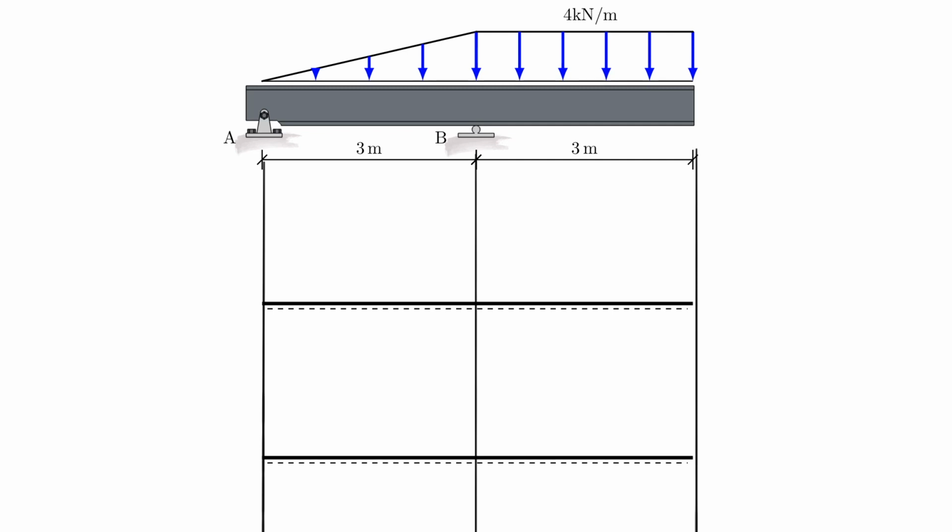All right, let's go ahead and start with the shear force diagram here on the top, which is also in kilonewton, and I like to actually develop them at the same time, so I also start immediately with my moment diagram in kilonewton meters. Now, what do I know? I know that all my diagrams always have to start at 0 essentially and end at 0, so I can already say that they are starting here, and the same is true for the moment, and it has to end up at 0 there as well.